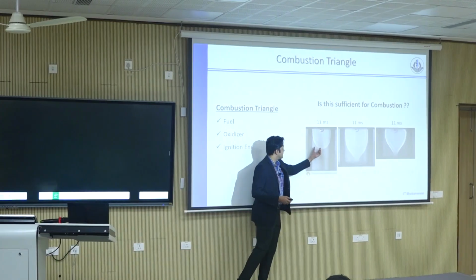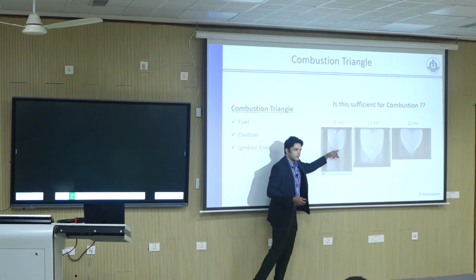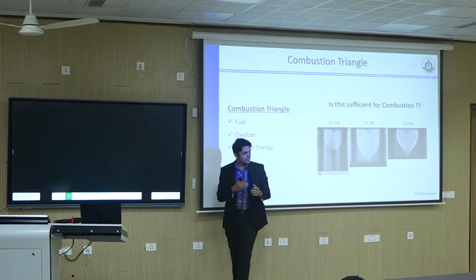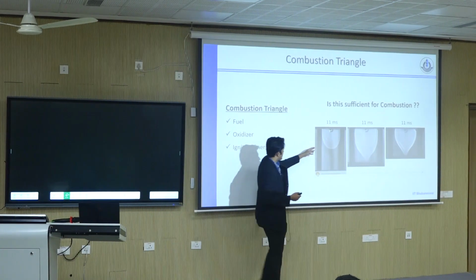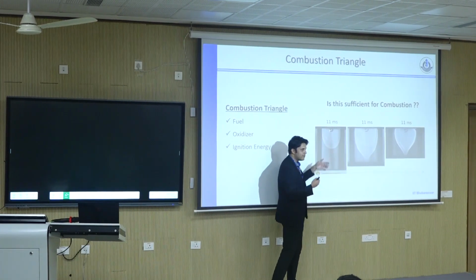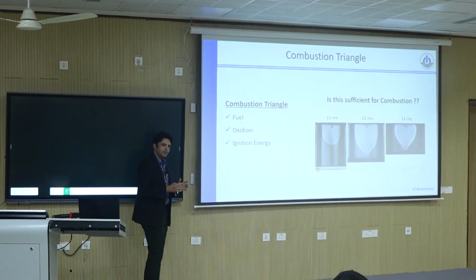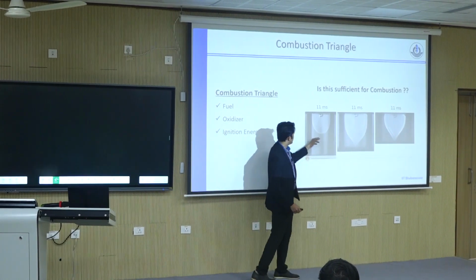It is locally releasing the heat, so that preheats the fuel air mixture that is sitting very close to the flame front. Once it receives that heat from the flame front, this zone ignites and you see the flame front propagating. So in basic terms, the mechanism of flame propagation is that you have a heat source term.